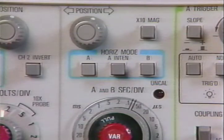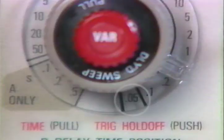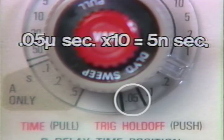The fastest sweep speeds of a scope are available with horizontal magnification. Magnification multiplies the sweep speed by the amount of magnification. On most scopes, the horizontal magnification is by a factor of 10. For example, 0.05 microseconds per division magnified by 10 times is 0.005 microseconds, or 5 nanoseconds per division. The 10 times magnification is useful when you want to examine parts of waveforms in greater detail.